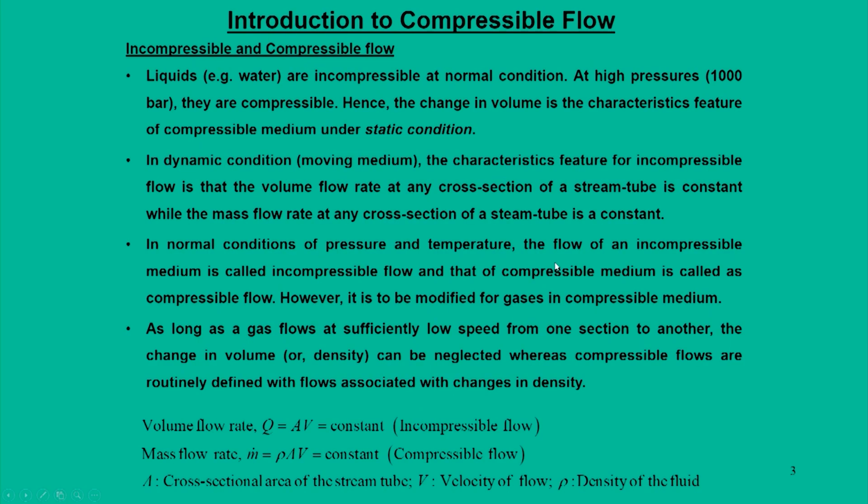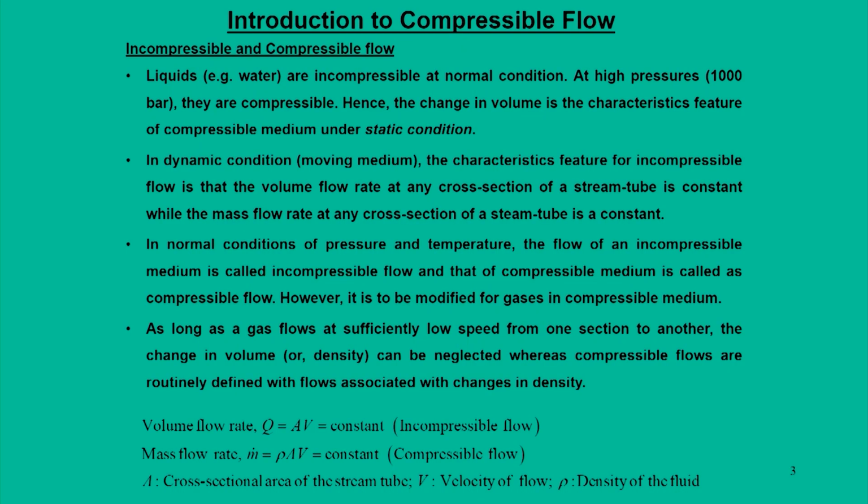In our previous lectures, we have completely emphasized the incompressible flow and compressible flow domain. There it was quantified that the compressible flow domain comes into the picture when there is a density variation of more than 5% and above. And under some circumstances in terms of Mach number, the flow behaves as incompressible flow, and for Mach number above a limiting value, the flow behaves in a compressible flow domain. So, what is that Mach number, we are going to find out.